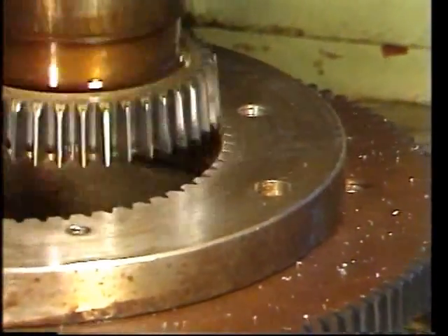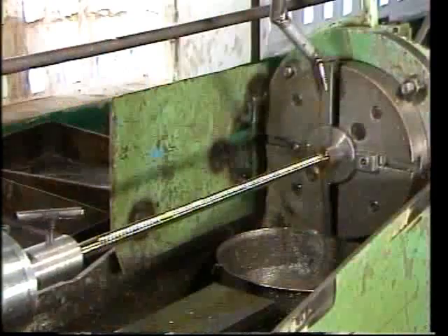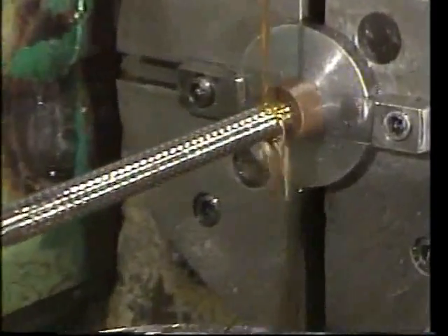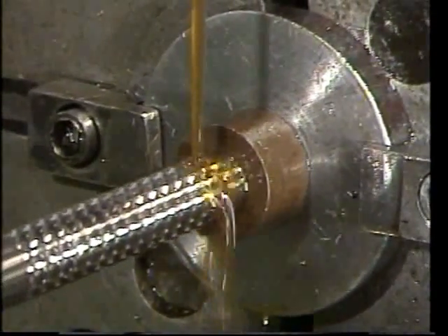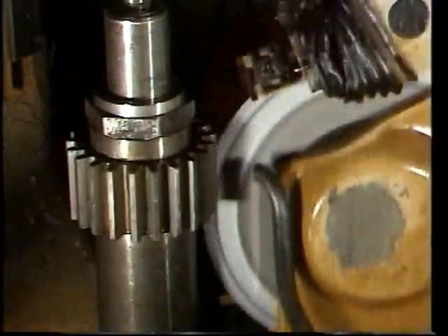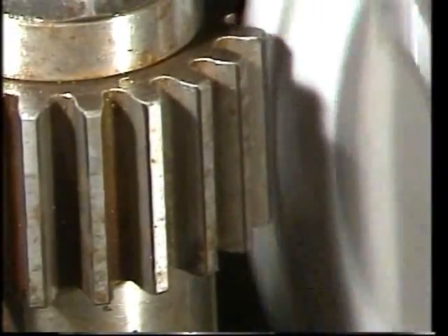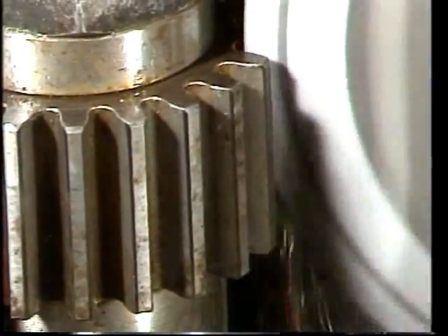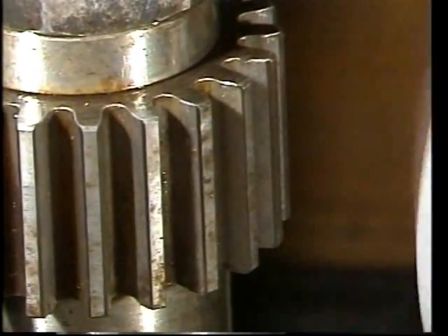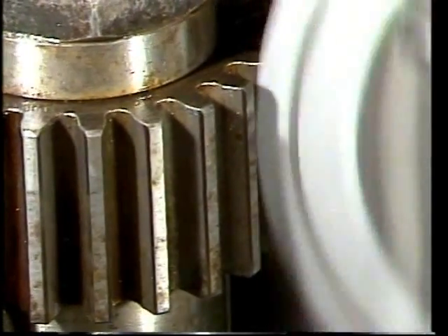Internal gears are produced for mass production by gear shaping using the pinion cutter. In case of large-scale production of internal gears in minimum time, broaching is preferred. A separate broach is required for every gear of different specifications. Spur gear teeth are subjected to finishing operations in specific cases where high accuracy is required, especially after the gears are hardened. Grinding process produces higher quality gear finish by removing tiny flats on the surface.